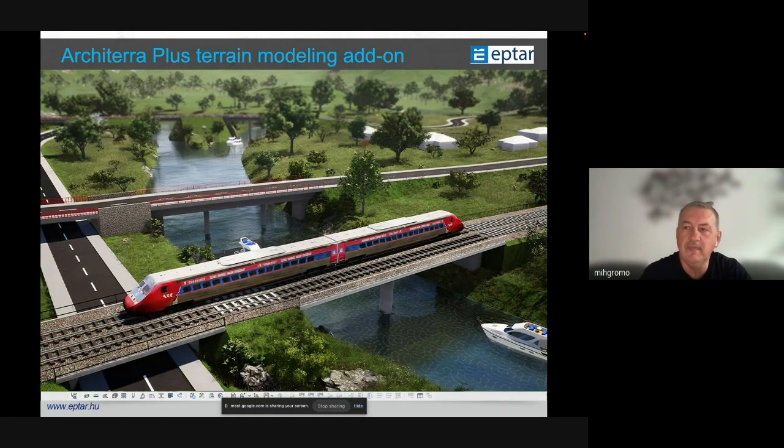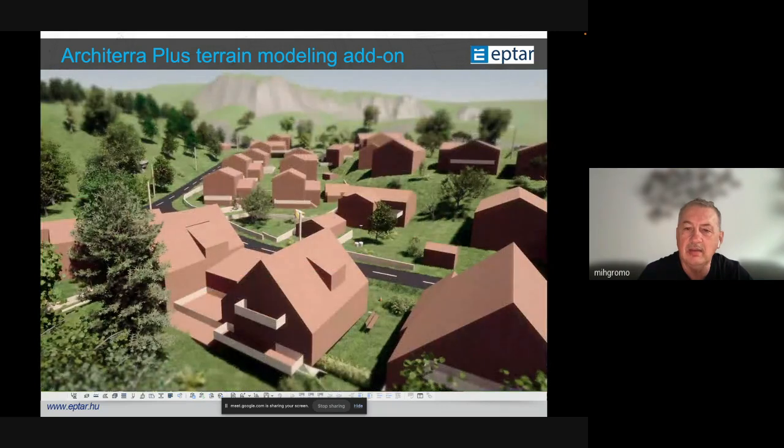You can assign a layer structure to the road, allowing an accurate cross-section representation. Similarly, you can place railways and platforms. For areas where earthworks are required, the program shows the excavation area in both 2D and the model view.